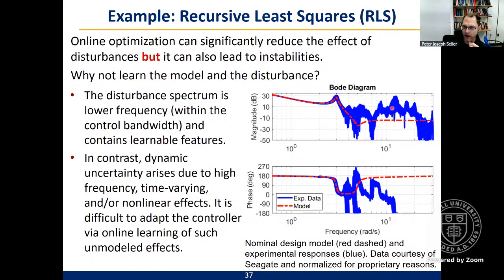In fact, the models that we have are really structural dynamics. They're really partial differential equations. It's really hard to learn things out here because the dynamics are actually changing in time, and there are nonlinear effects. A lot of the results where you're learning the model also assume maybe you have a finite state dimension. That may be, or appear to be, a benign assumption that I believe the dynamics are finite state dimension, but really things like time delays, structural dynamics, which are partial differential equations, these are infinite dimensional. There really isn't a finite dimensional model that they'll learn here.